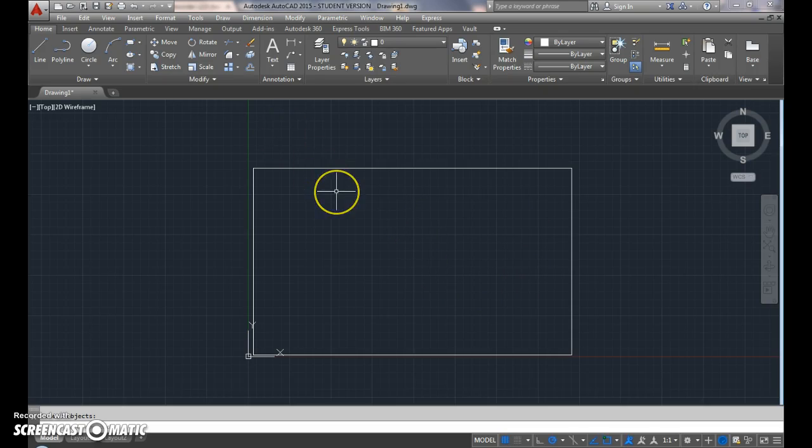That number comes from several different factors. The first key factor is that a 2x4 stud wall is fairly common building material. The 2x4s themselves are actually 3.5 inches wide, and then you throw a 1/2 inch of drywall on the inside of the house, bringing you up to 4. And then your exterior siding material can consist of several different layers of things, bringing it up to usually around 5 to 5.5 inches in width.